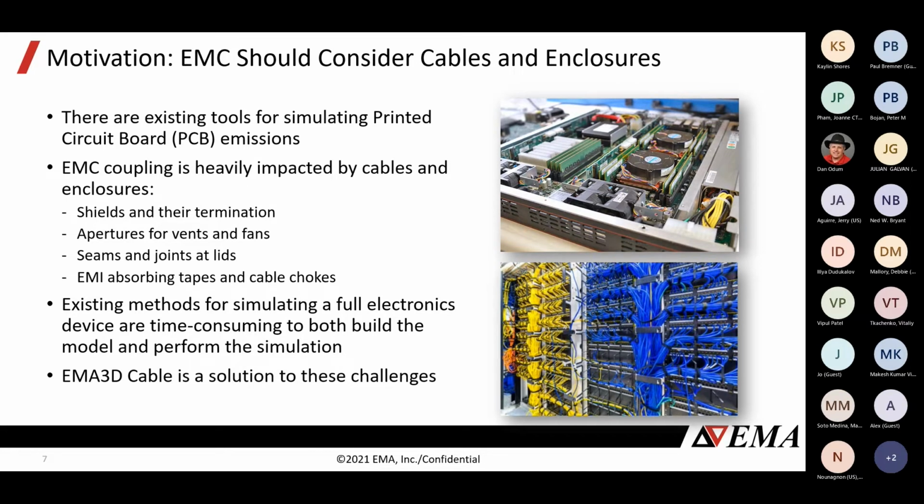Okay, the motivation here. There have been on the market really great tools for simulating printed circuit board emissions. For example, Ansys SIwave, Ansys HFSS, best-in-class tools for PCB emissions. But those emissions are heavily impacted by cables and enclosures. So when we do EMC testing, we're not testing PCBs levitating in a vacuum. Those PCBs are installed in real enclosures, and those enclosures have cables in the enclosures. There are cables outside the enclosure. The cables penetrating through the enclosure affect the emissions.